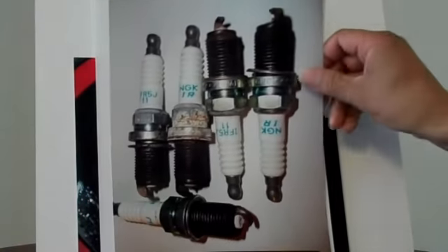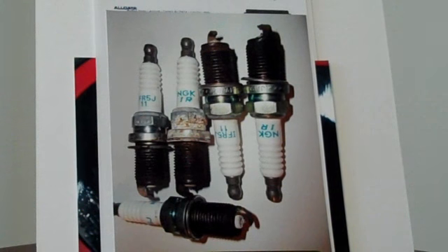Diagnostic trouble code P0305, cylinder number 5 misfire. This vehicle was first brought in with 130,640 miles. The maintenance chart shows replacing spark plugs at 60,000 miles. Step 8 in the pinpoint test says to remove the spark plugs and visually and physically inspect the spark plug for a faulty condition. Replace spark plugs due to overgapped.